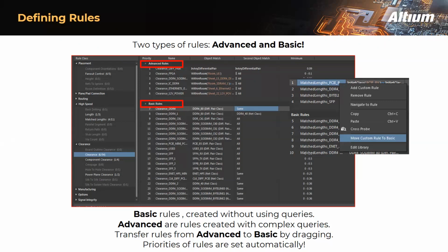You can see earlier in the legacy rules and priority, we had to prioritize the design rule while routing a particular net class. Whereas in this advanced editor, the tool will automatically prioritize the rules based on its category, and it will likely apply to the particular net or net class while routing.